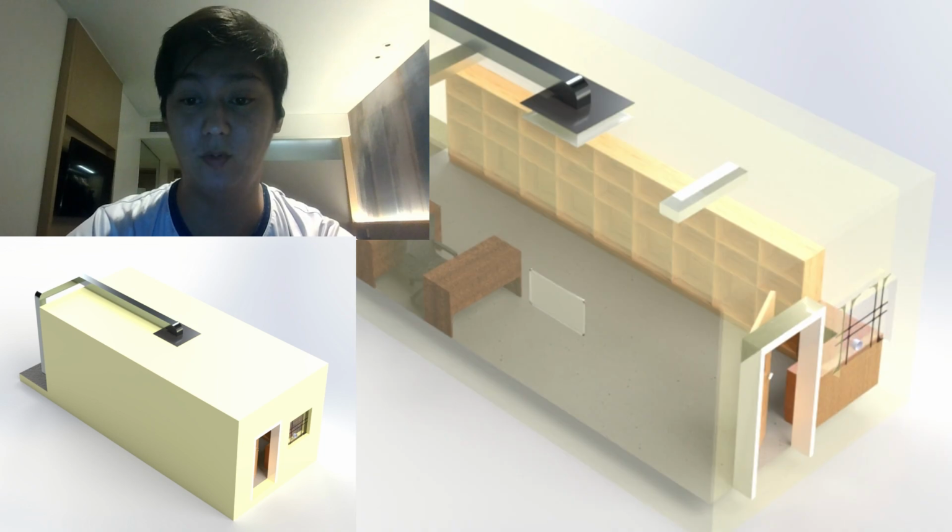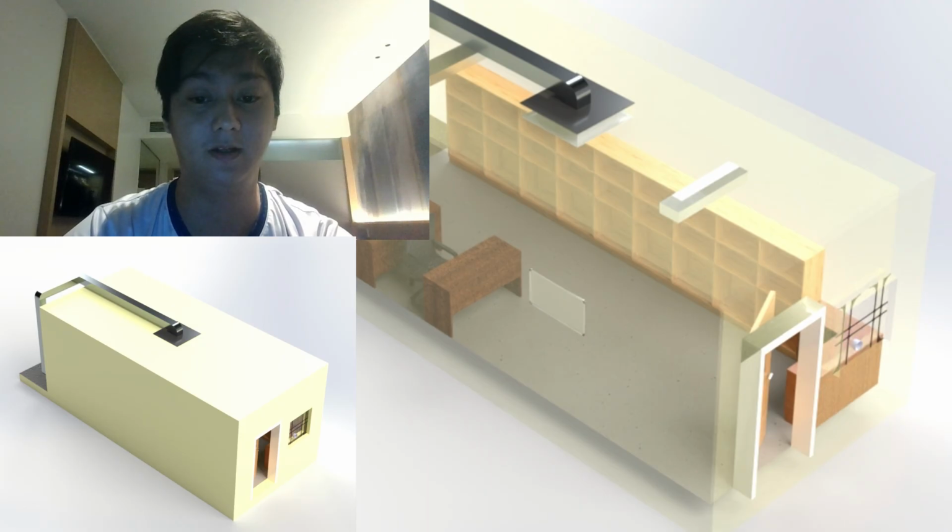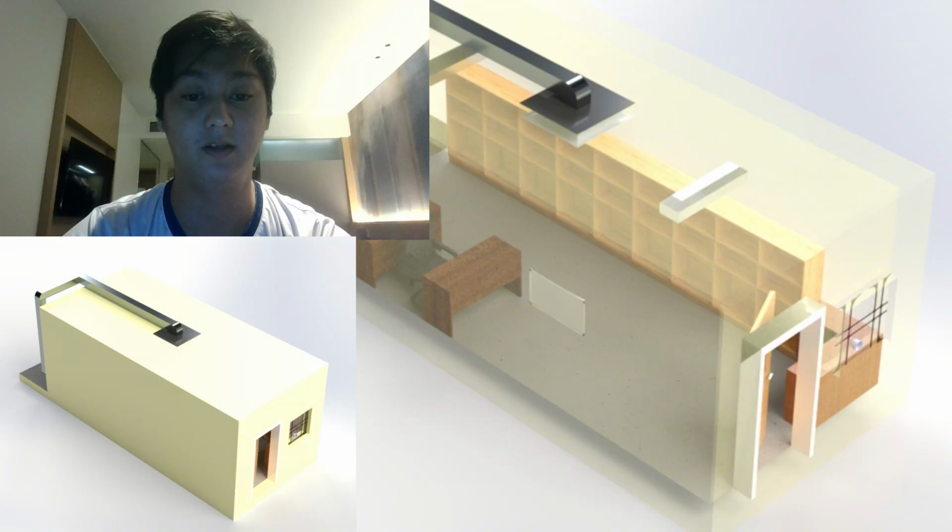You may ask, why do you go through the trouble of a ducted system for a single room? Why not a simple wall-mounted split type? The answer lies in the physics of the room. As I mentioned earlier, we have a huge floor area and an exceptionally high ceiling at 3.4 meters. A standard wall-mounted unit would only effectively chill the air immediately in front of it. It would struggle to mix the air in a volume of 100 cubic meters.